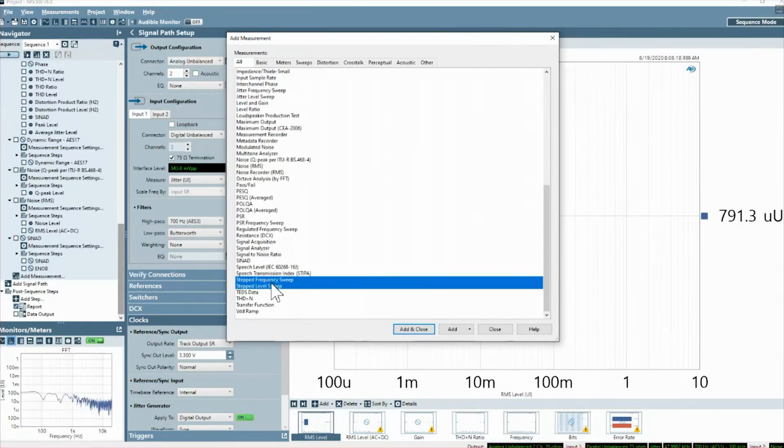interface can be used. As far as the physical interface, it goes a little bit beyond the scope of this webinar, but we actually have an upcoming webinar on this topic. You'd have two choices. You could use the ASIO interface potentially to bridge across to USB, or you could use what we would refer to as open loop test, where essentially we would record or play back WAV files and then analyze those WAV files. Those are both potential solutions to that problem.